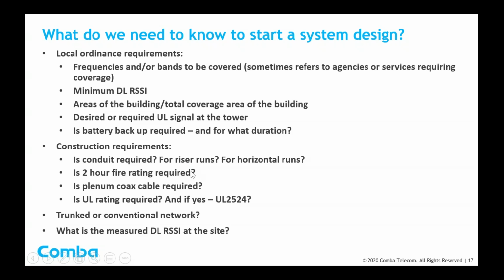Is 2-hour fire rating required? Sometimes they say we want the head end equipment, meaning the BDA or the fiber DAS head, to be in a 2-hour fire rated room. That's all they ask for. Other times they'll say, no, we want the horizontal coax to be 2-hour fire rated. So again, you need to know that because all these things will play into the design that you're going to do. Is plenum coax cable required?